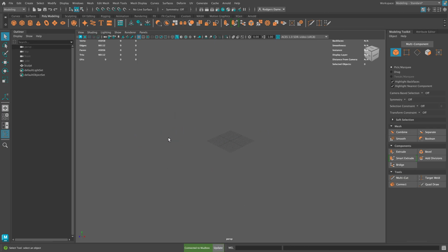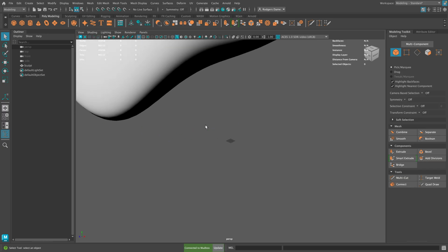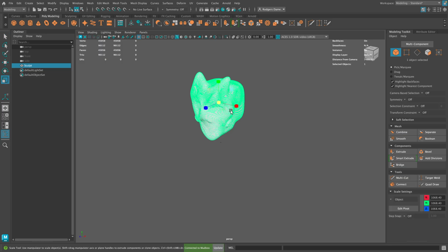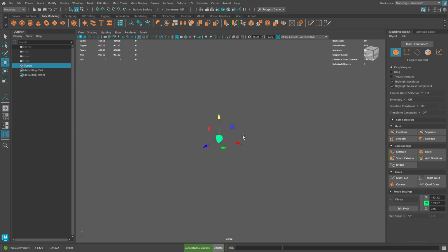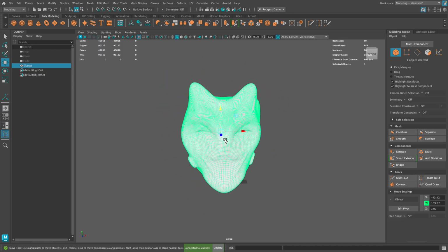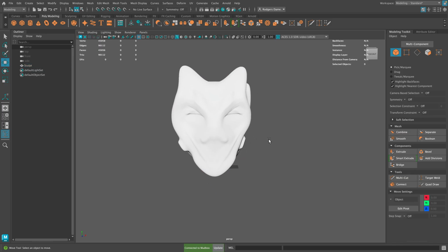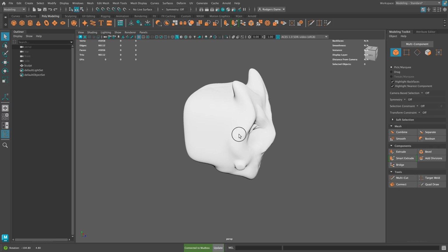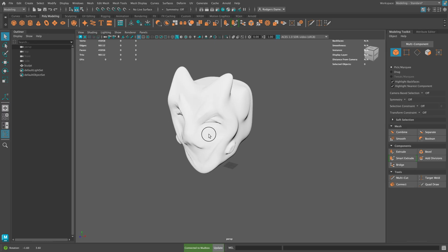Let's zoom out a little bit and see if I can find my object. There it is. The object might come into your scene as a really massive thing, so remember, I can just scale that back down and press F and frame it up. And so from here in Maya, and this will be the conclusion of this tutorial, what we would hypothetically do if we wanted to turn this into a model that we could rig later on is use the quad draw tool.